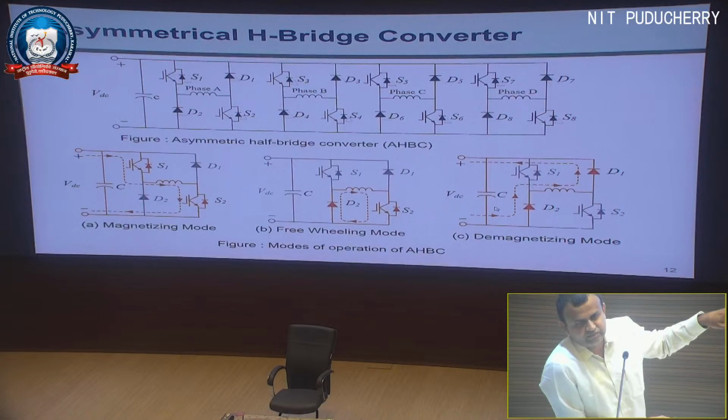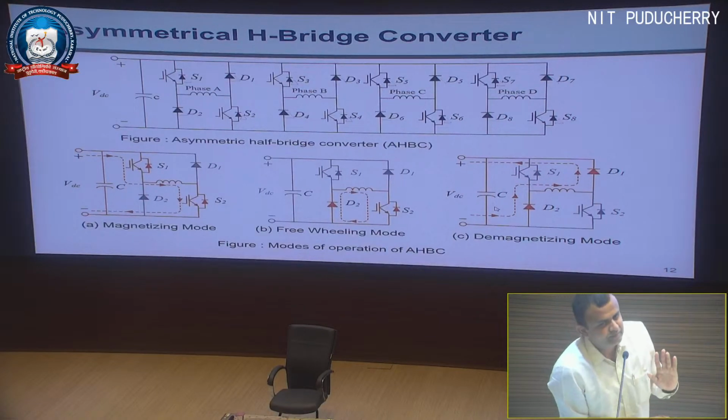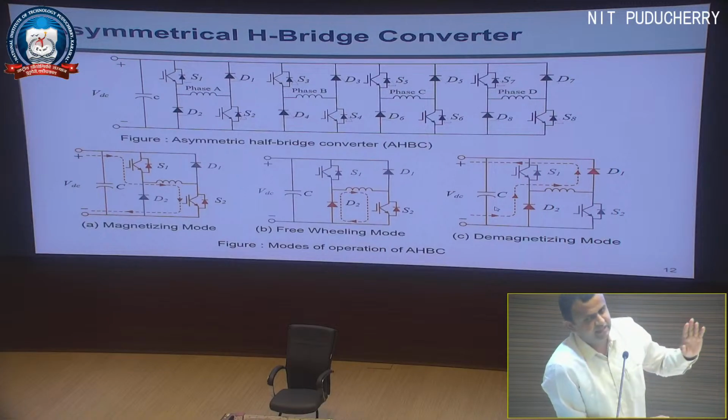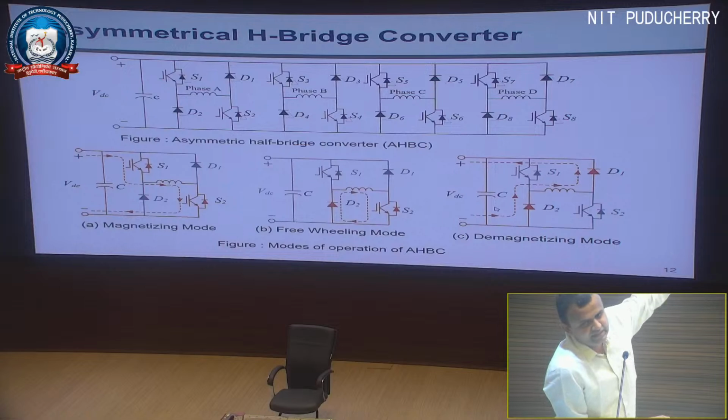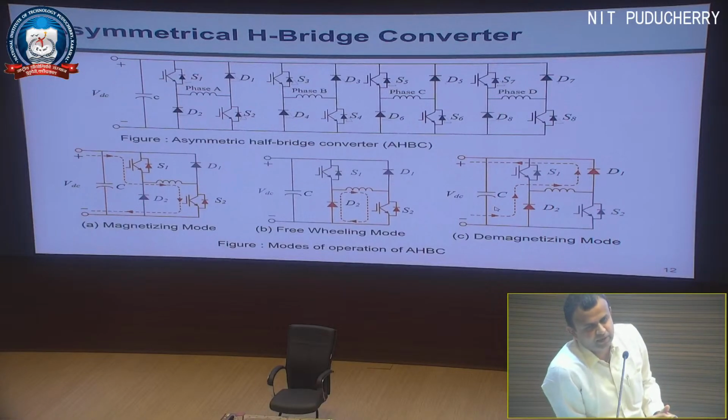Yes, if you have an inductor in this case, for example, the trapped energy, when the switch is off, can go back to the supply through the diode. Okay, in that way it will also protect the switch.